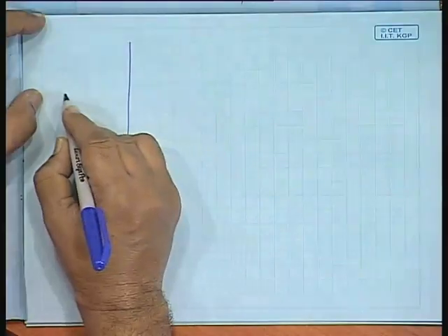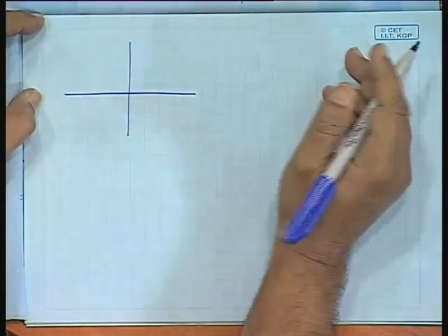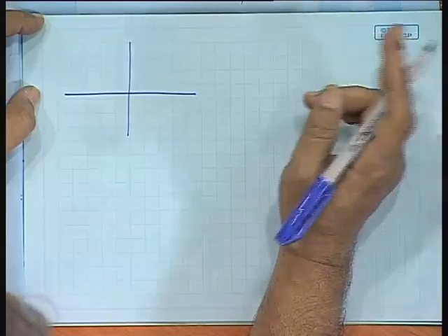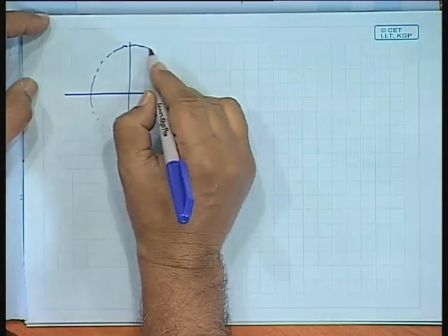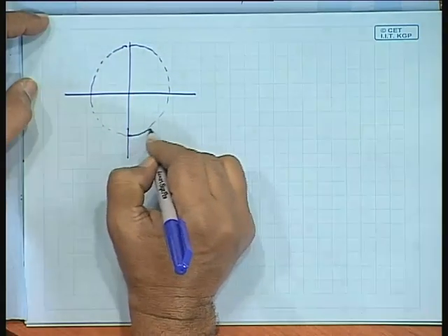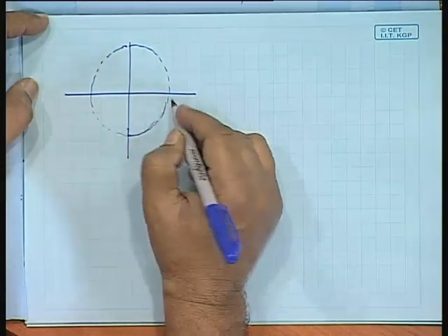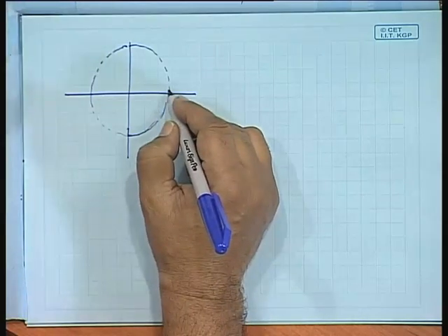So, n is equal to 6 will give me the roots placed at an angle of 360 degrees divided by 2 into 6, 12. So, 30 degrees, all right. So, even number of roots, if you remember, we discussed earlier, even number of roots, 6 roots on this side. So, there will not be anything on the real axis.